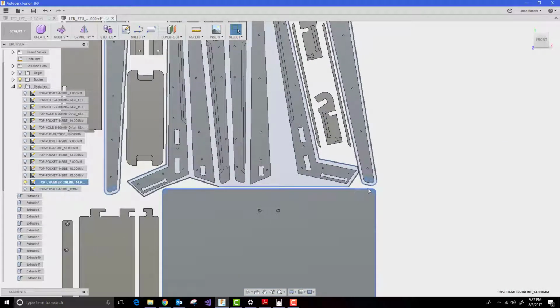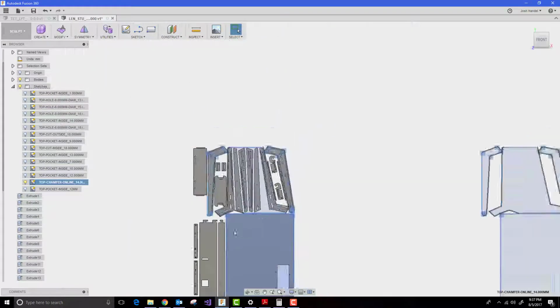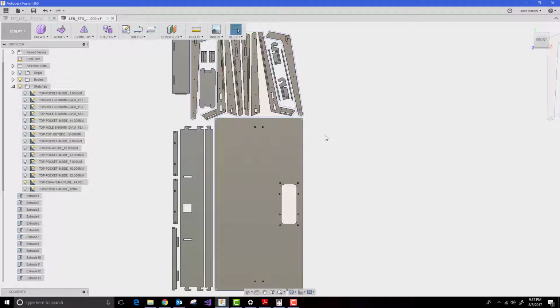And then they want to do a chamfer on the actual tabletop itself. Remember I mentioned take a good look at the tabletop, because if you look really carefully right here, you'll see there's that 14mm chamfer. It looks like a 45 degree, so a 90 degree bit, but that could be a 60 degree bit. That could be whatever bit. I can't really tell you what bit it is. Could be a 90, could be a 120, could be a 60. They don't actually tell you either. So a little bit of